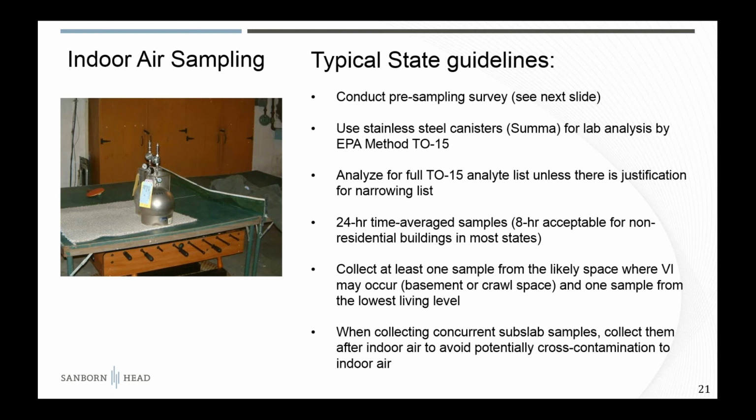And then many states, of course, want you to do concurrent subslab and indoor air sampling, but what you should be doing here is collecting your subslab sample after you collect your indoor air sample, so you don't have cross-contamination of subslab vapor into indoor air as a result of drilling that hole through the slab. So on the first day, set up your SUMA canister, come back the next day, 24 hours, finish up that sample, and then do your subslab sampling at that point.